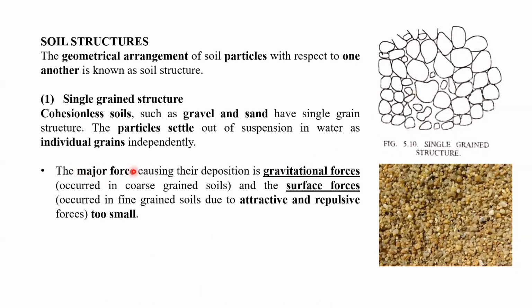You see, the major forces causing their deposition are gravitational forces, which are also called mass-derived forces. We have also talked about how coarse grain soils are deposited by the mass-derived or gravitational forces, and the surface forces occur in the fine grain soil due to attractive and repulsive forces, right?